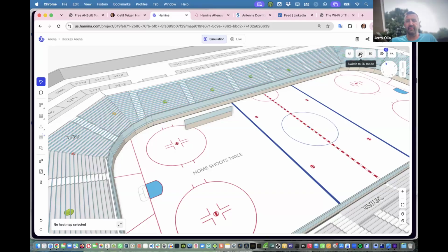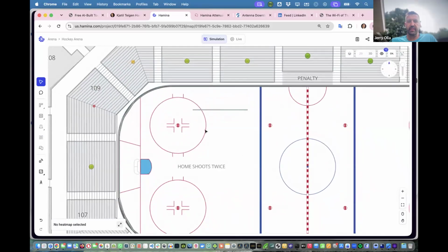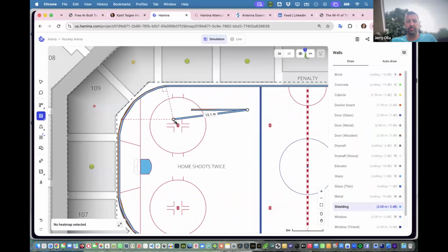If it was a full-length wall, what we're trying to prevent is the user shooting themselves in the foot by drawing two drywalls on top of each other, or a brick wall on top of a drywall, and then it gets messy in that way too. So you're going to end up with double attenuation. That's essentially what it's trying to avoid you doing. But in these cases, you want to double up those materials, because you're not actually doubling it up. It's just a different attenuation or different material on the bottom than on the top.